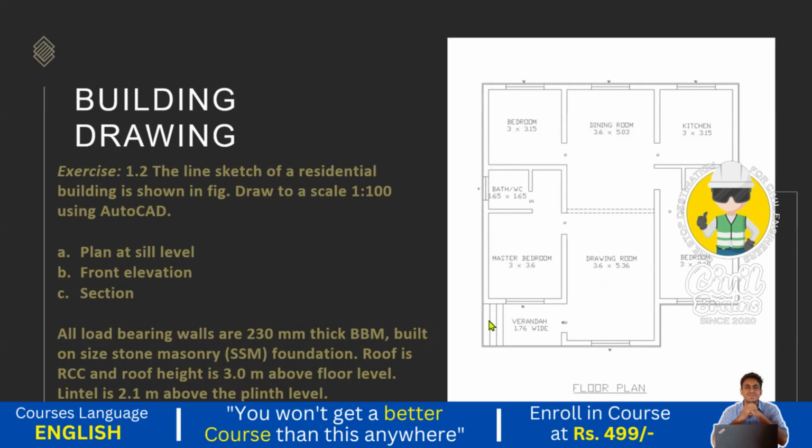Okay, so what is the procedure? First we need to calculate the outer dimensions, x or length and the width of the room. That is the first step of doing the planning. Once we calculate the length and width of the room, the next step is we need to draw the outer line, or outer wall, of the particular building. After that, inner walls we need to draw using the offset command.